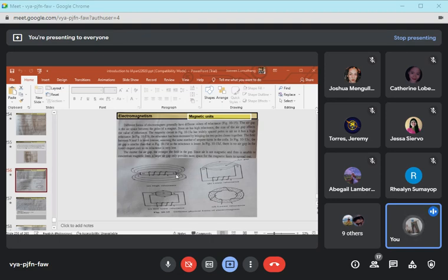For figure B, the reluctance has been decreased by bringing the two poles closer together. You will see the North Pole and then the South Pole. The field between these poles is more intense, and that is why the reluctance is lower. Unlike in figure A, where there is high reluctance because of the widely spaced poles in the air.